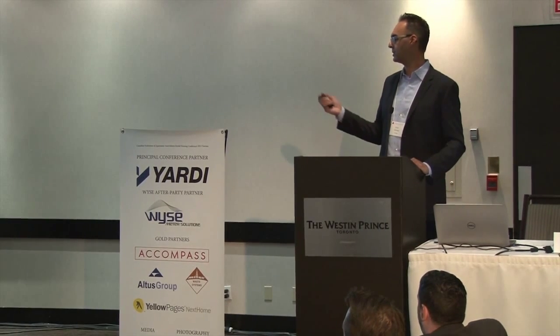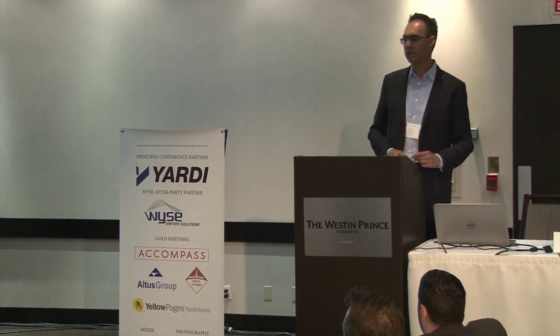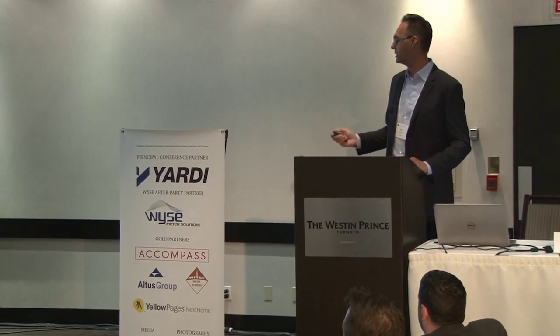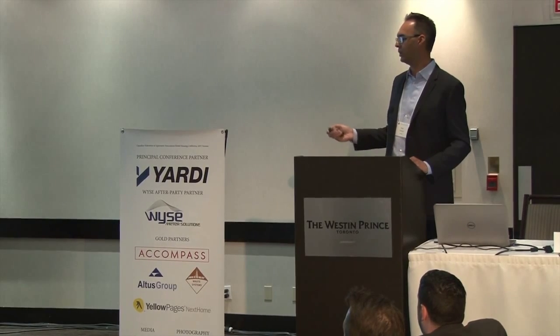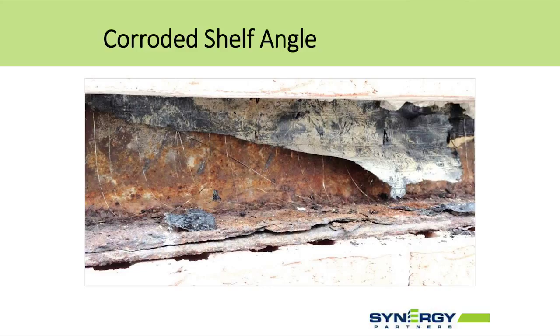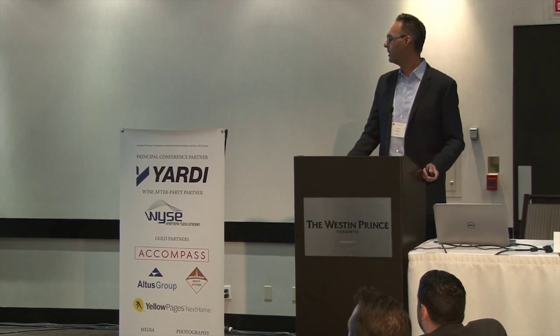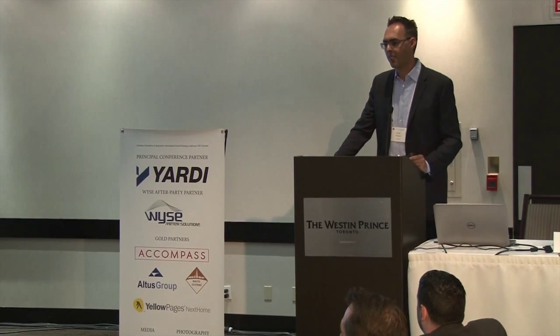If you start to get those stacking effects or loads being compounded within your wall assembly, you will have other issues such as cracking, spalling. You can have brick panels that start to bow and come loose. And so it's important to get that looked at. I just got a slightly better picture of the amount of corrosion that's happening within this wall assembly, and it is fairly significant. So, what's the solution here for that building?